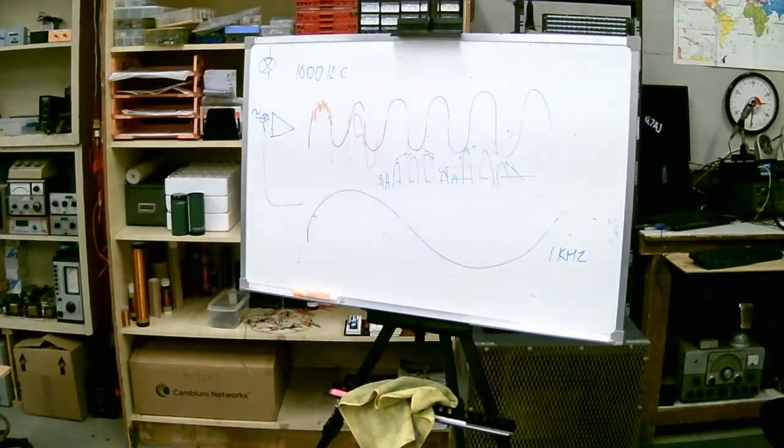It's 20,000 hertz, and then the fuzz in between is the carrier. Expanded out, you can see the carrier there. That's the radio frequency, because it's in megahertz. Each one is changing amplitude. If I reduce the audio to nothing, you can see.